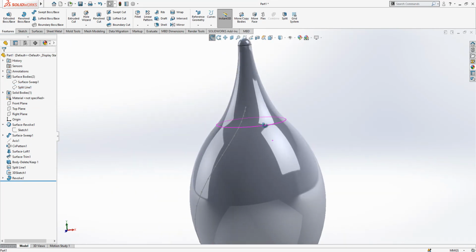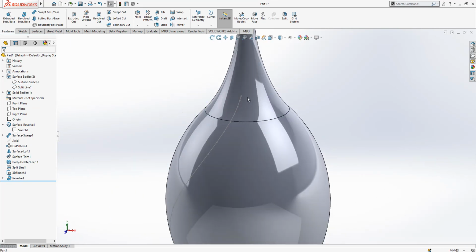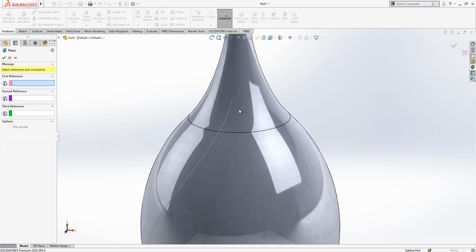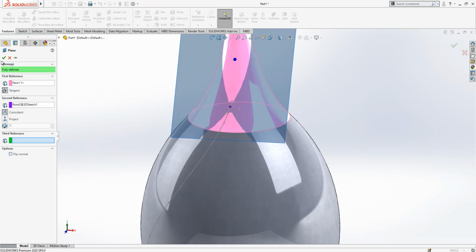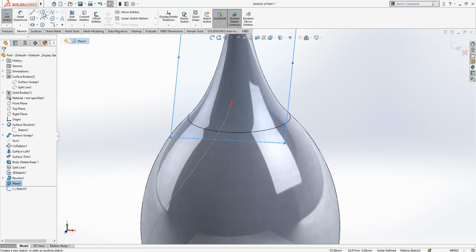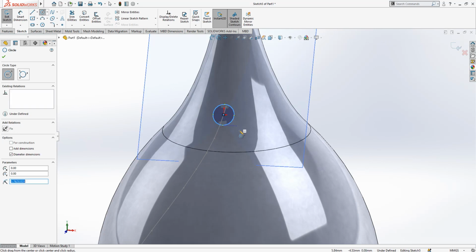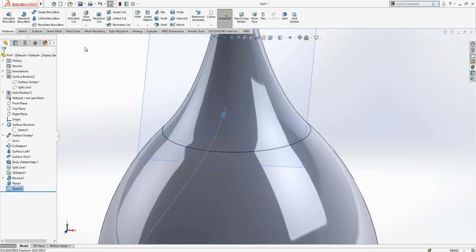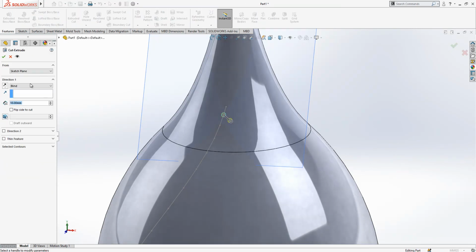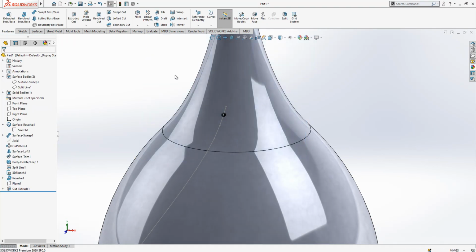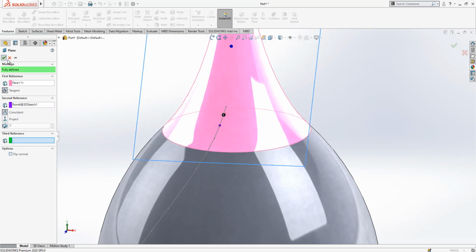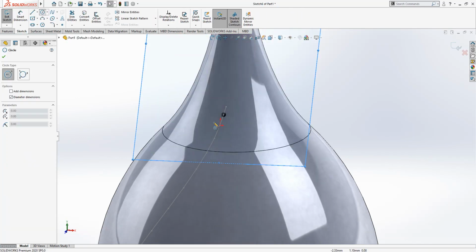Yes. Now what we are going to do, creating on each point a sketch plane and then cutting the body. Select surface and we select point. First hole will be 1.5, 1.5, equals sketch, extrude cut, mid plane. Each time same operation. Can be a bit boring, but at the end we are going to get really something nice.